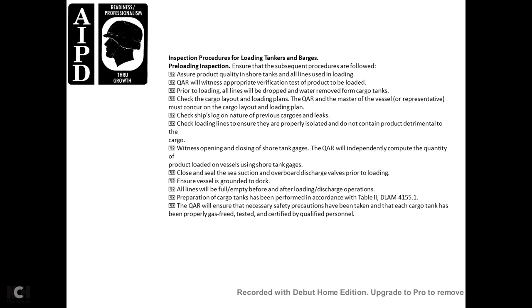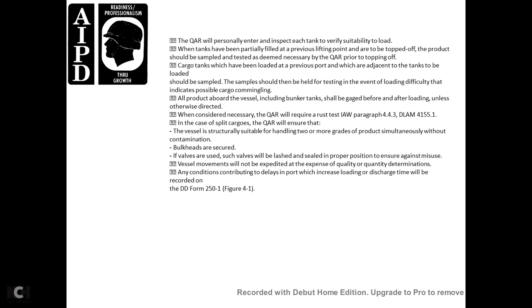Ensure the cargo tanks have been prepared in accordance with table 2, DLAM 4155.1. The QAR ensures that the necessary safety precautions have been taken and each of the cargo tanks has been properly gas-freed and tested, certified by qualified personnel. The QAR will personally enter and inspect each of the tanks to verify they are suitable for loading.